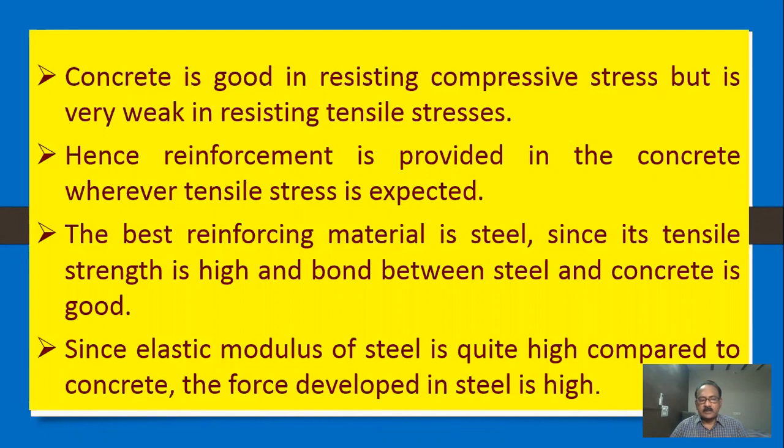See, if we look at the reinforcing material, that is steel, its strength is high, and the very important point is the bond between steel and concrete is good, and the elastic modulus of steel is quite high compared to concrete. The force developed in steel is high. So this is also one of the important points.